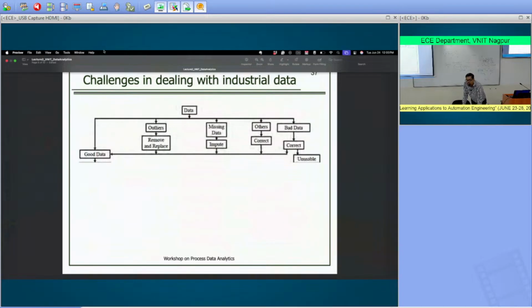Yeah, so I think there's a subtle difference between what I'm saying and what you're saying. When I say outlier, it is a measurement that is unlikely to have come from your process. Okay? In that example, they're not quite outliers, they're abnormal events. There's nothing wrong with the sensing. There is nothing wrong with the measurements I've collected. My sensors are working fine, the measurements seem reasonable within limits. But the product that I made in that particular batch is not of high quality, so I can't use it, right? But it's not really an outlier in the measurement. An outlier in the measurement is a measurement that couldn't have come from a real process.